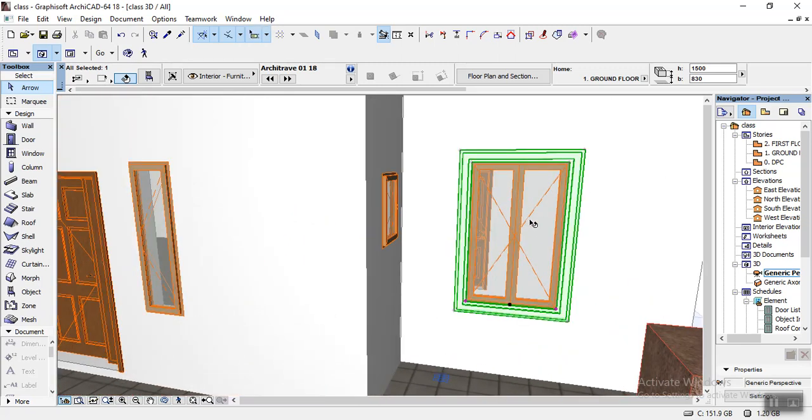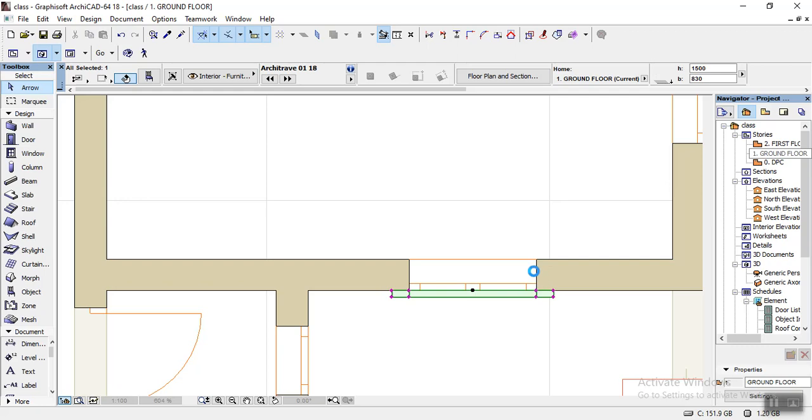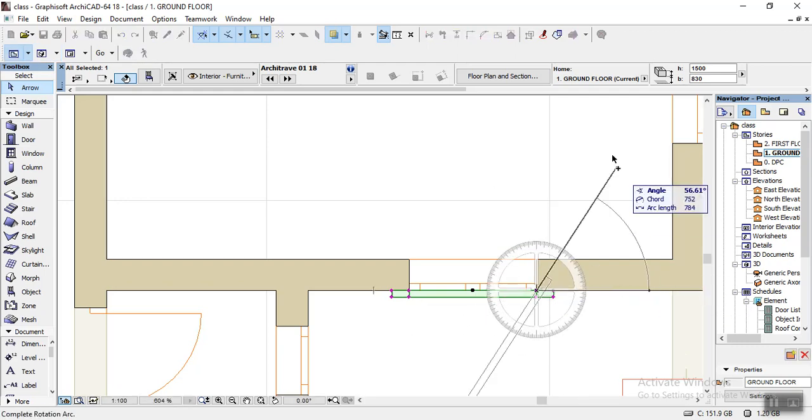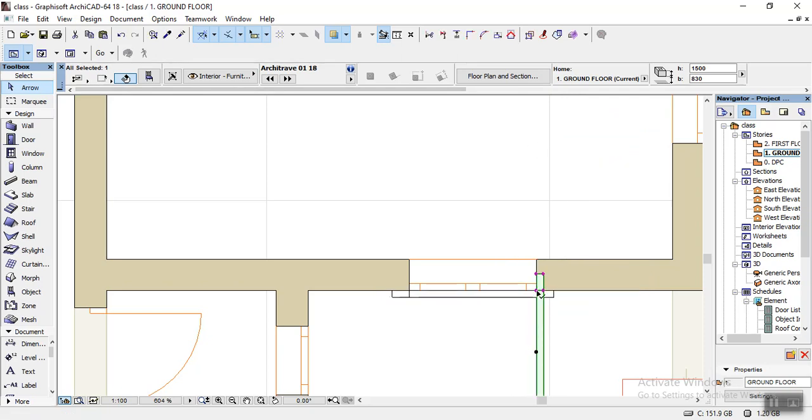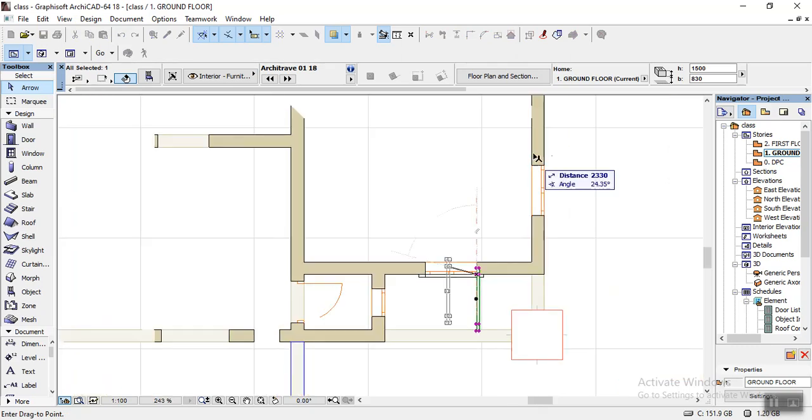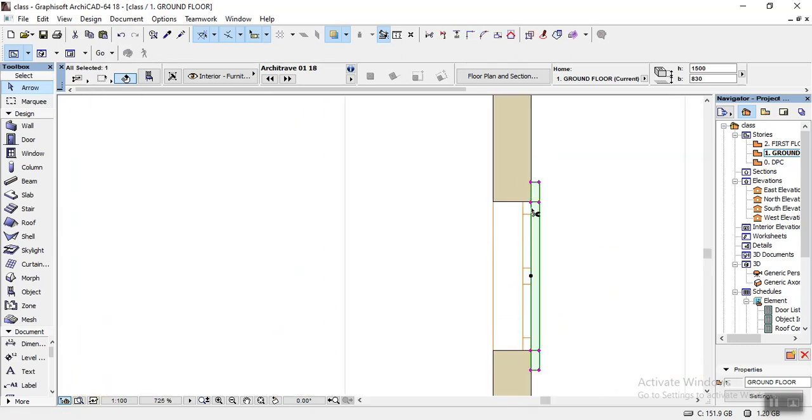The same command you use on the window has to be the same command you're going to use on the wall extra, so it can fit in perfectly. So all I just need to do is copy this and paste it in. Rotate it. You rotate a copy. Then you paste it in all the spots where you have 900 windows. So let's say I have a 900 here. I'll copy again.